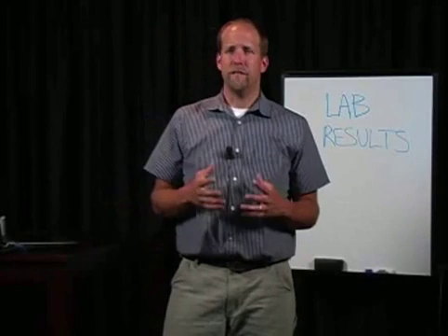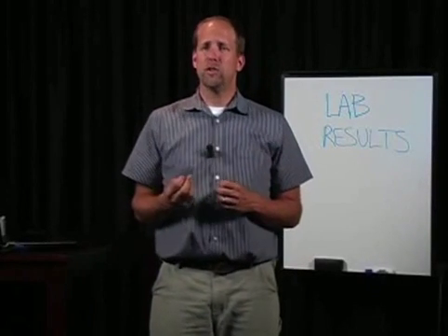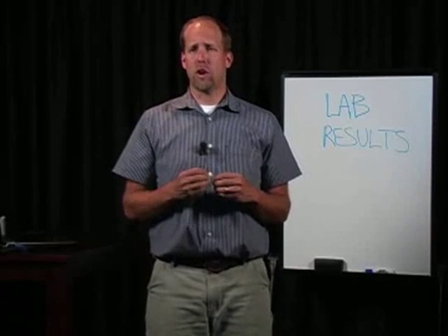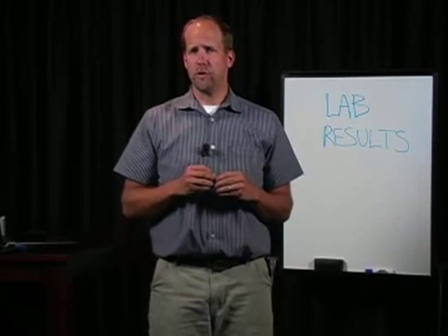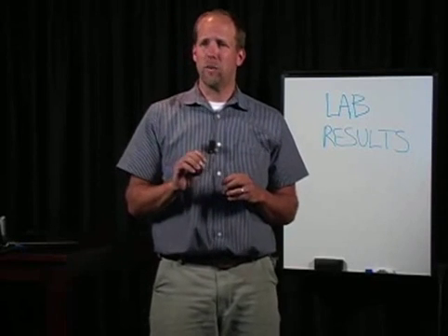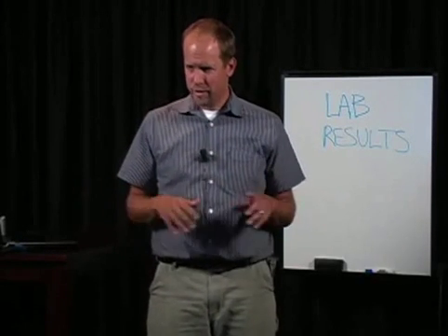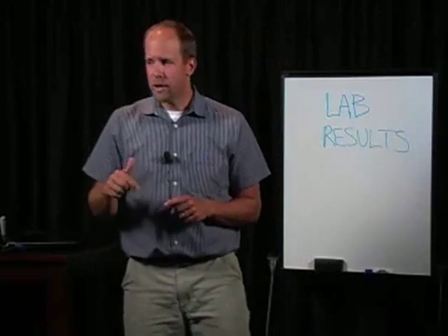A wet vacuum. Wet or water extraction vacuums are designed to collect water. They can be used to remove water that has accumulated on floors, carpets, and hard surfaces. Wet vacuums should be used only when materials are still wet, otherwise they may spread the mold spores. Wet vacuums alone will not dry carpets. Wet carpets must be pulled up and dried and then reinstalled. The carpet padding must also be dried. The tanks, hoses, and attachments of wet vacuums should be thoroughly cleaned and dried after use because mold and mold spores are sticking to the surfaces.